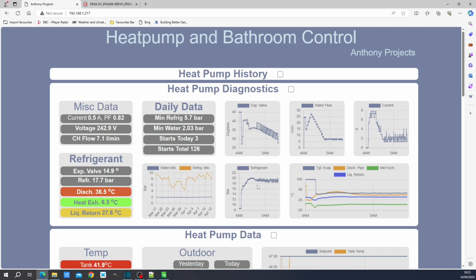example. Once the output from the heat pump has settled down to its minimum here, you can see 1.3 amps here. You can see the expansion valve is now rapidly opening and closing very quickly. And as it rapidly opens and closes very quickly, you can see that the refrigerant pressure is becoming unstable. And this is the unstable regime where the compressor output is not sufficient to draw flow through all of the expansion tubes, or all of the capillary tubes.